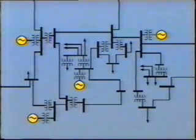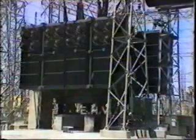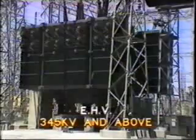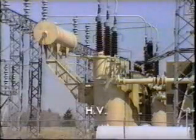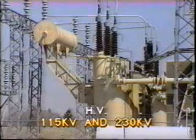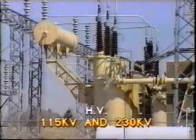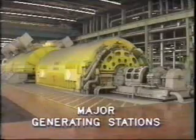As a general rule, most utilities find that they can adequately monitor the system by installing recording machines at every station in the extra high voltage range, that is 345 kV and above, and every other station in the high voltage range, such as 115 kV and 230 kV. This allows at least one end of each high voltage line to be monitored. They are also installed at every major generating station, and every station with interconnections to other systems. Normally, oscillographs are not located at the distribution substations, except those installed to analyze special problems or to conduct research.